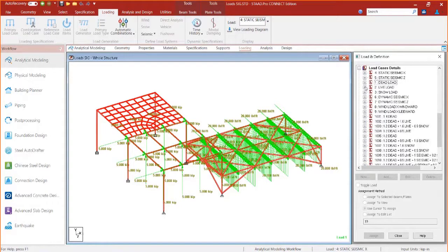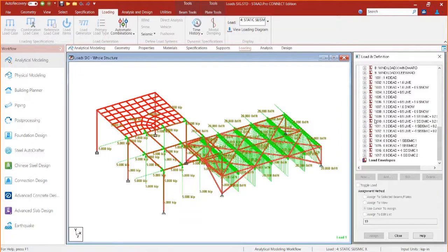And here I can review the information. I can review the load combinations that were brought over. I know that these are repeat load cases because I have my red L adjacent to them. If they came over as traditional load combinations, I would see a blue C next to them. That's kind of your indication where you can see after the fact what was created.